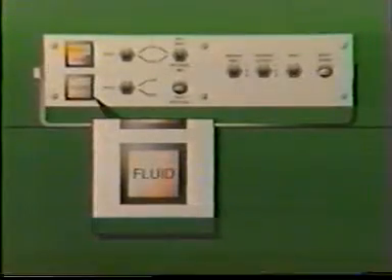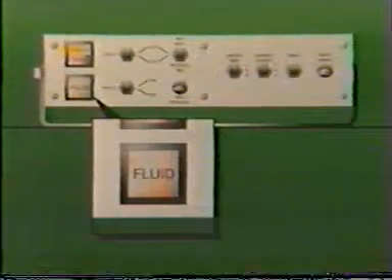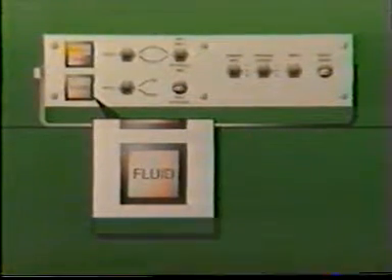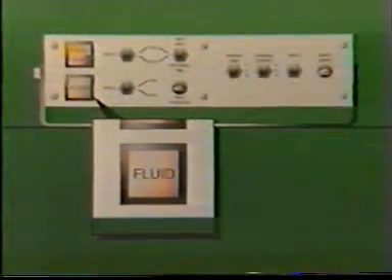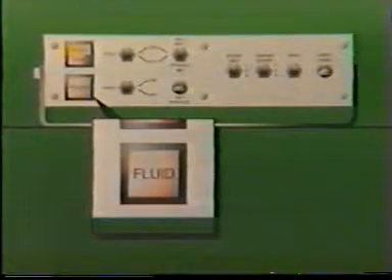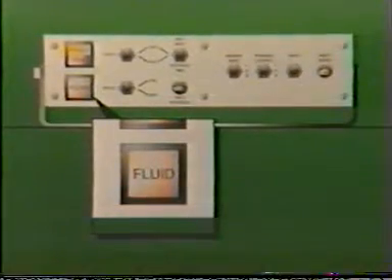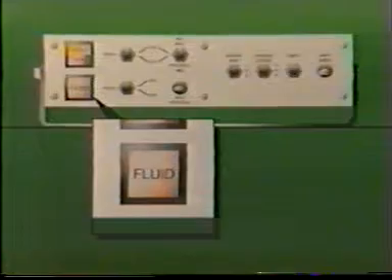The first level of protection is the engine protection lamp. When a parameter being monitored goes out of bounds, the ECM lights the engine protection lamp and logs a fault. The engine protection lamp is the operator's first indication that a system parameter is out of bounds.